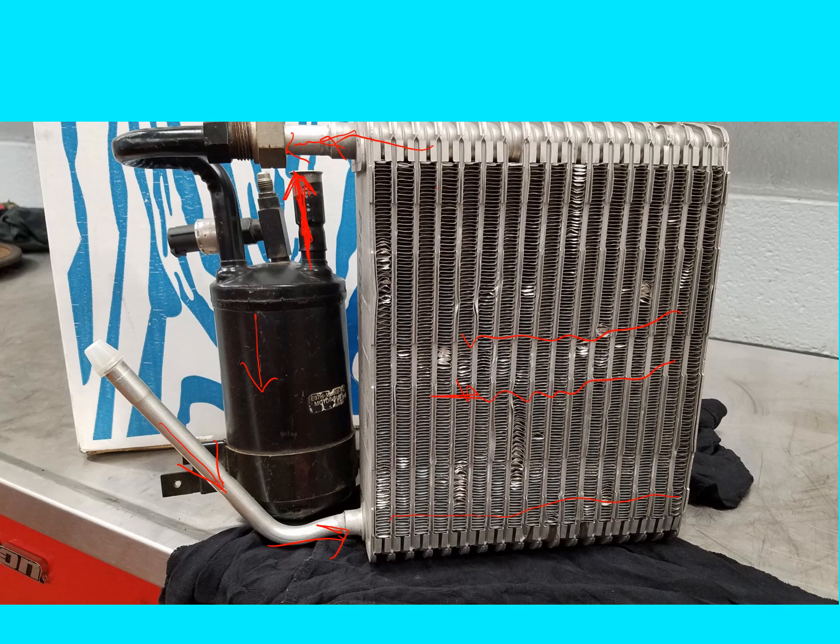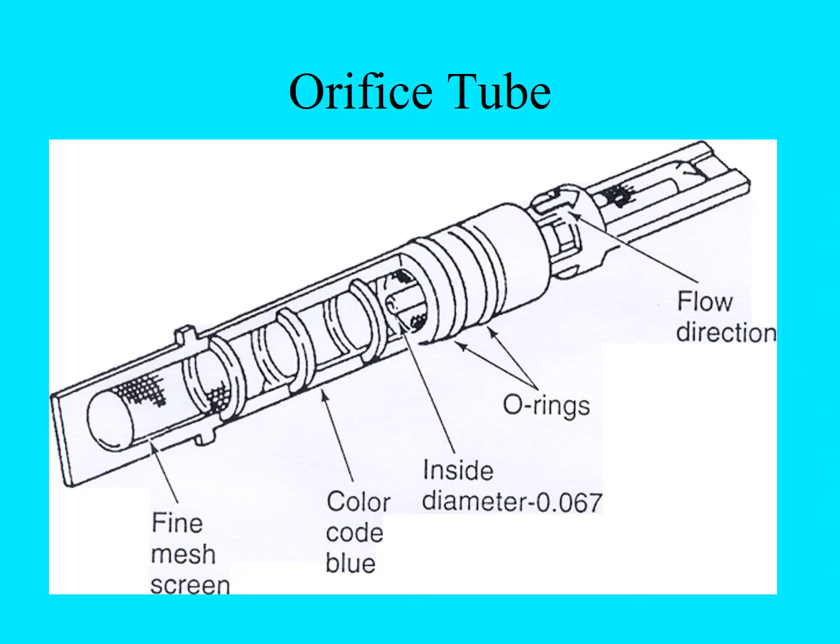This is being shown there. So this is just a picture of the evaporator core. And the evaporator cores are basically identical for a TXV system or an orifice tube system. The only difference would be the connection that would be used in this area here for a TXV system. So this is one of the restrictions that would separate the high and low side.